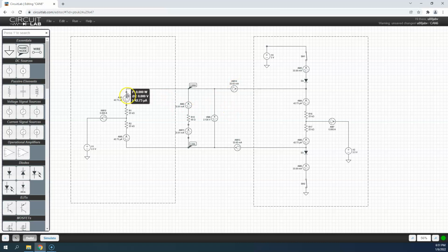So we can see some of this current is flowing down here. None of it, absolutely none of it, flows over here to the 2.5 volts, because this point is held at 2.5 volts. It has to be. You can't get to this because you can't put your meter here, but I'm going to go ahead and throw one here just to show this, because it's kind of like, why is there no current flowing back to there?